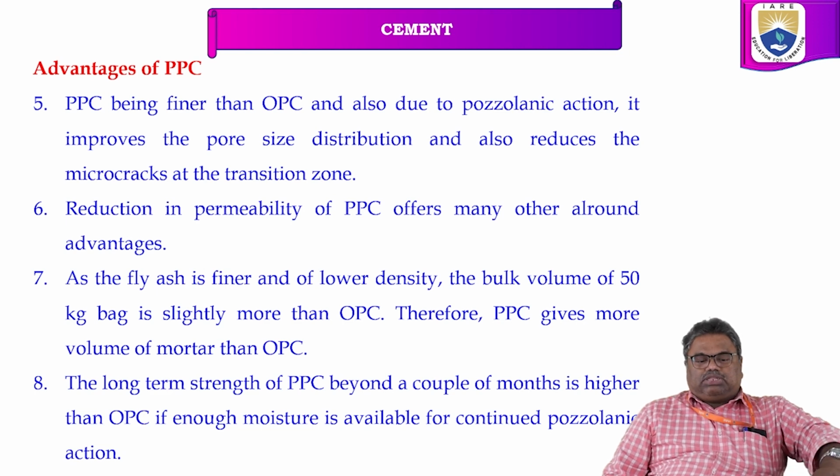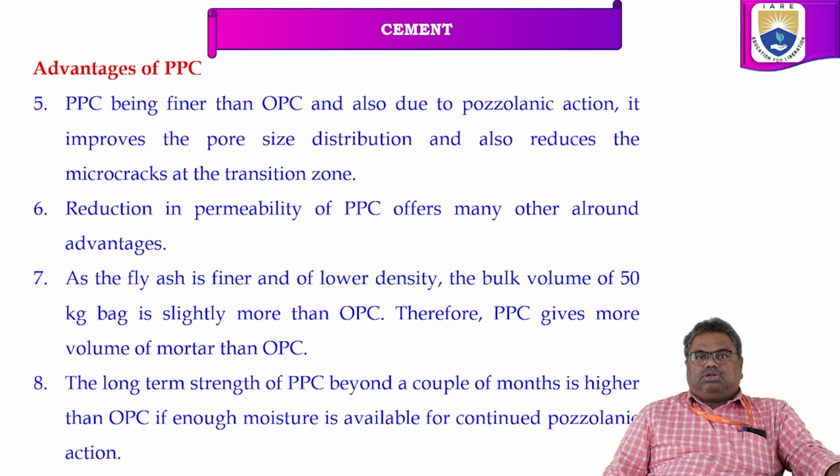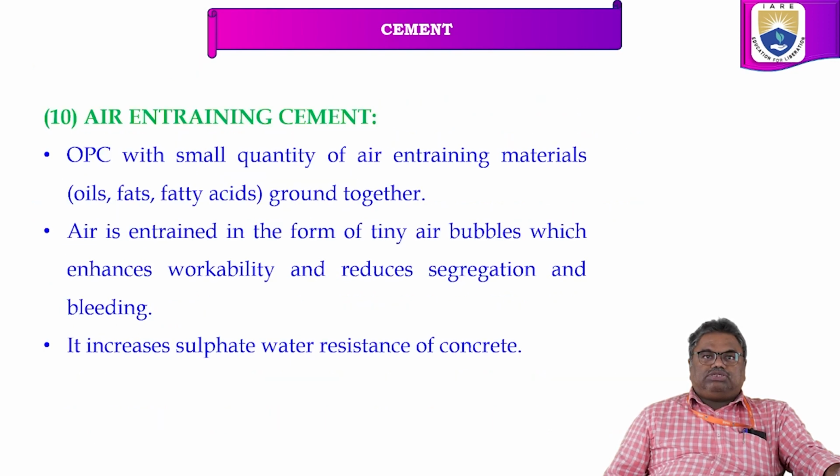The long-term strength of PPC beyond a couple of months is higher than OPC, if moisture is available for continued pozzolanic action, right? So if it is under water, if moisture is present in the concrete, the hydration process will continue in the case of Portland pozzolana cement used in construction. So this is about Portland pozzolana cement.